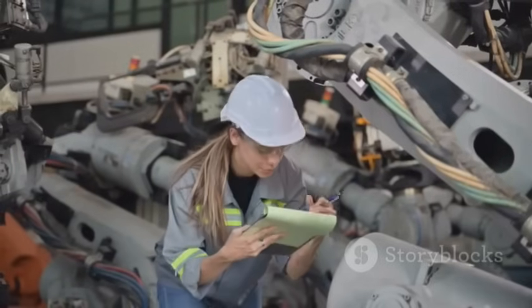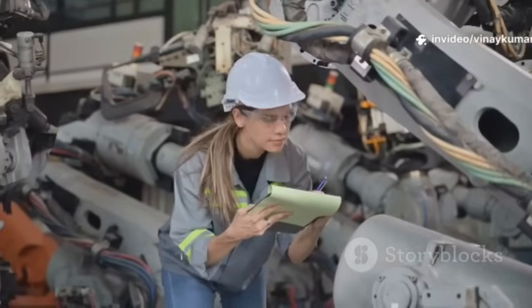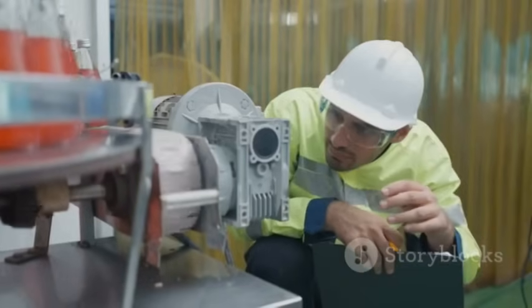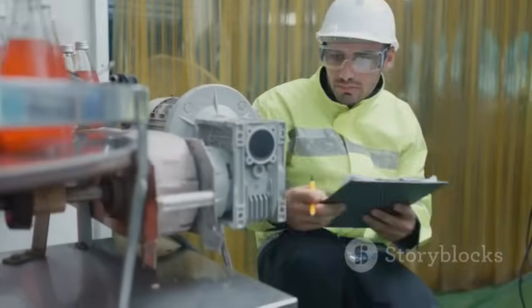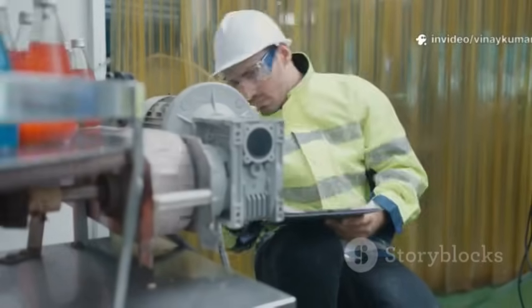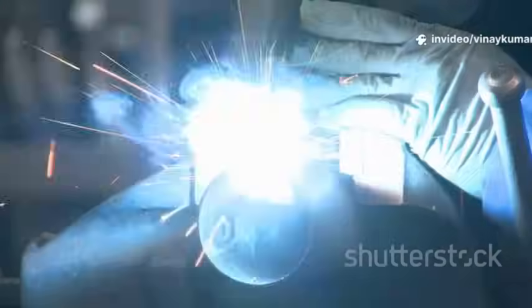For each piece of covered equipment, the employer must establish and implement written procedures for maintenance. These aren't just generic fix-it-when-it-breaks instructions. They are detailed procedures to ensure that maintenance is performed consistently and safely, preserving the integrity of the equipment. This includes things like proper torque for bolts or specific welding procedures.